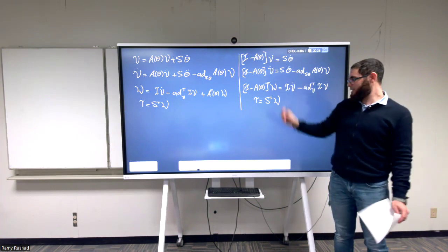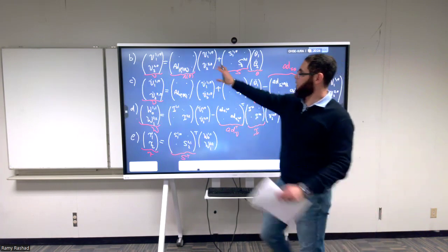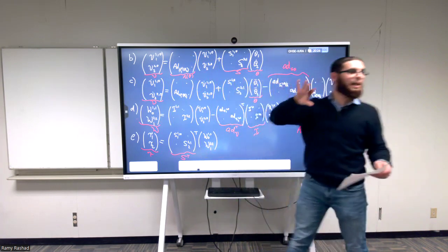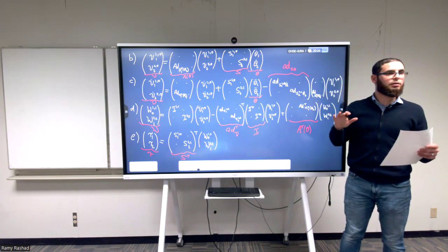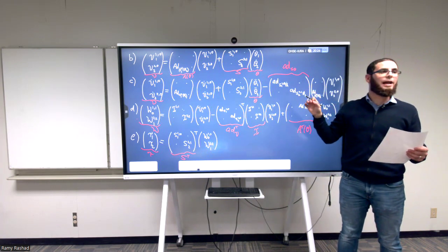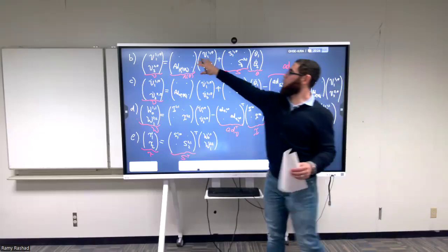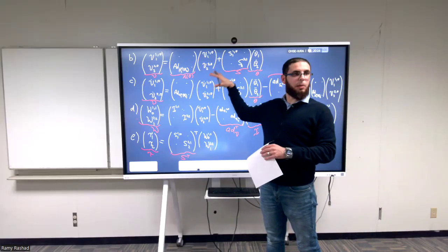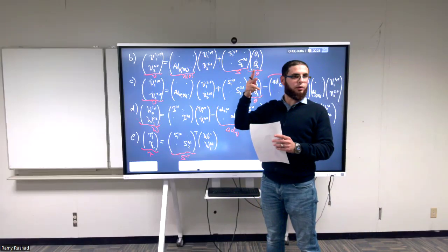The A of theta, this special structure that it had, is what's known as a nilpotent matrix, if you ever heard about it. It's a nilpotent matrix of order n. Here in this example it is 2, because we had a 2-link manipulator, right?